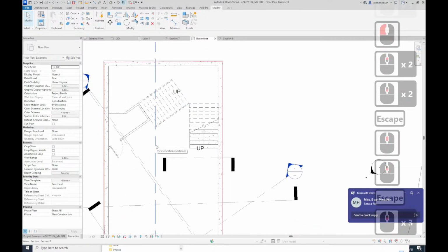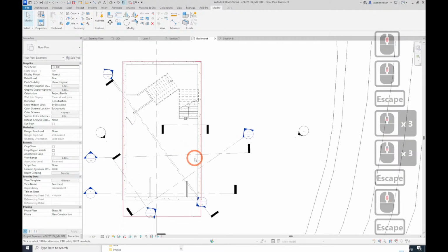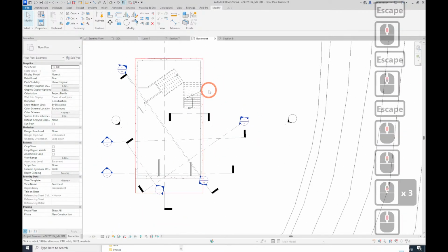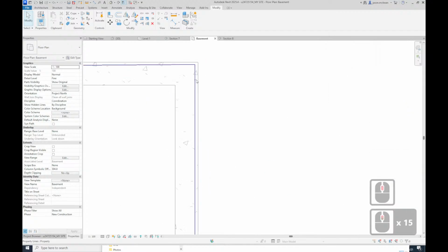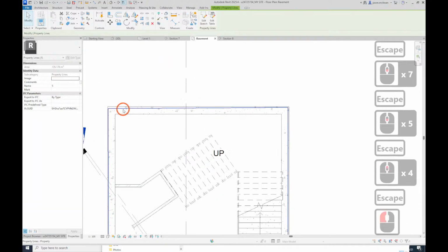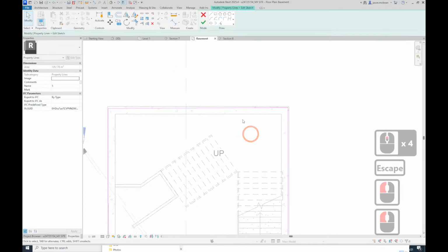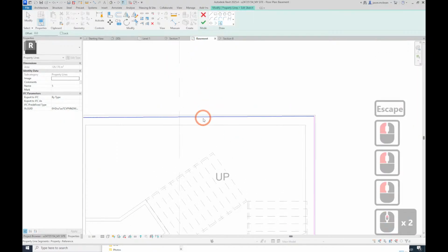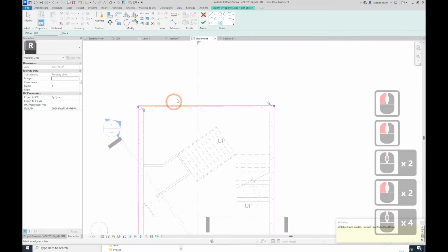But it's actually easy to fix now because your walls match. You align everything, everything must be around your property line. But what you can do is, if that's slightly skew, make it square, provided it doesn't go over your property line. Maybe just tweak your property line. Yeah, okay, I'll do that. Tweak your property line to suit. How do I tweak? That's easy. Edit sketch, and then you go align, watch. It's actually this easy.